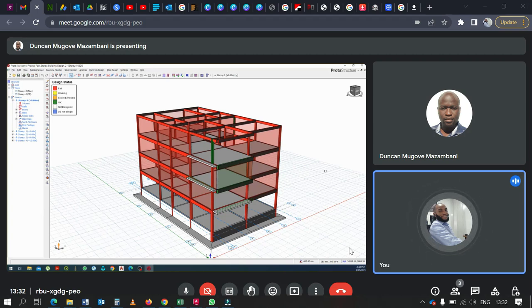But it's not well done. Even in manual design, we don't design the staircase as we design the building entirely. We design the staircase separately on its own. That's why we always keep that staircase hall area as a void, so that we can design it separately and then just come and fix it there during construction. So we do staircase design separately, not alongside the building.